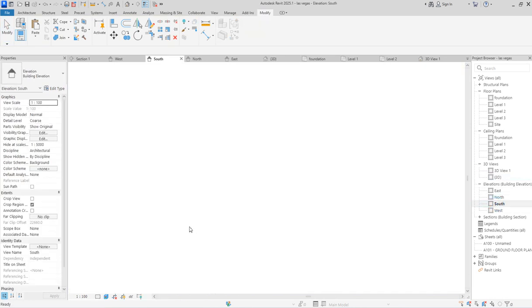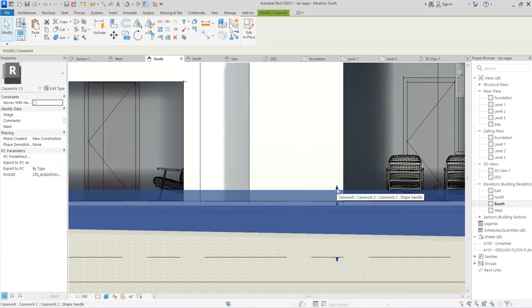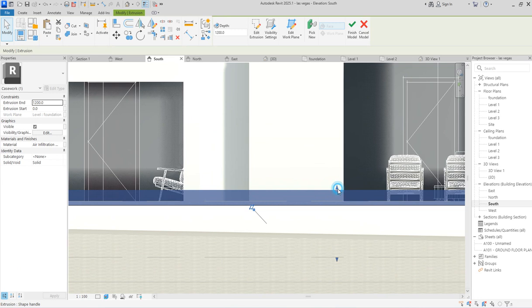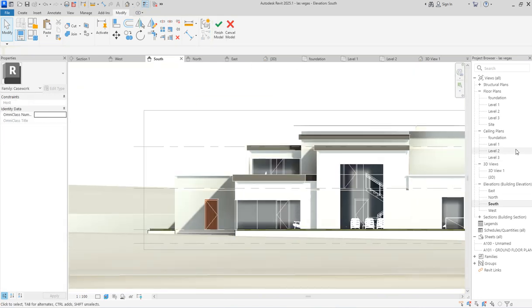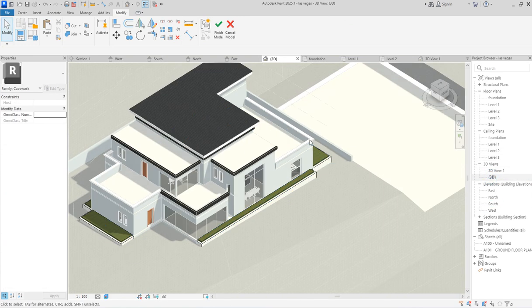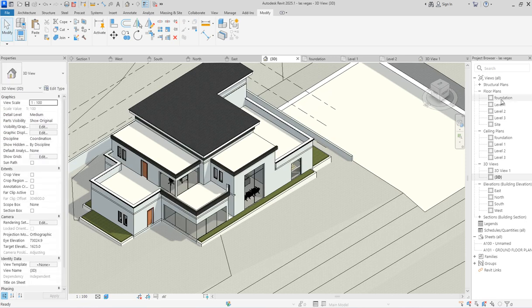Go to Site. I'm in this place, so I want to just reduce it. Edit, and select this, so I'm dragging it down. Good for me. I'll see it in 3D again and see that it's not at the normal level. So I click Finish on that. You can now begin to bring flowers onto it.